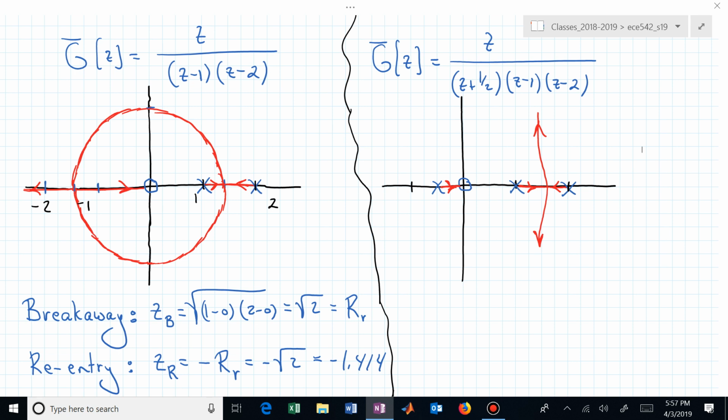Where these 2 real poles lie to the right of 1 real 0. In that case, we have a circle with the 0 at the center of that circle, and we figure out the radius based on how far each of those poles are away from the 0.